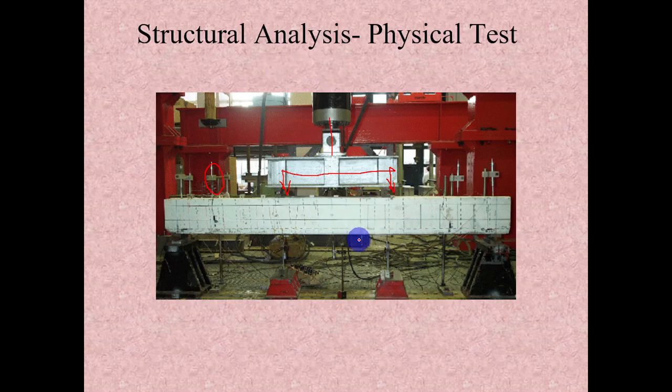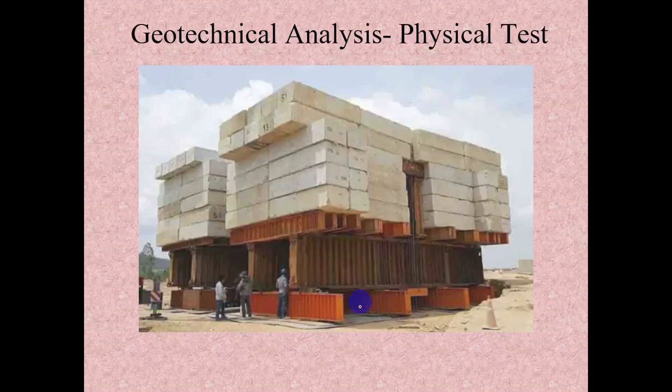Another way of physical testing is to analyze the foundations or the supporting soil. What we are seeing here is called a pile load test. Usually, we design the pile using empirical equations. Pile design means structural design is separate.